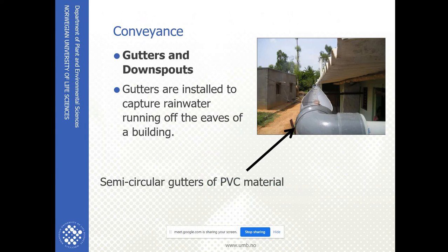Disinfecting rainwater: rainwater can be used for drinking. It is clear, has no or very little taste or smell, and comes from a well-maintained system. Rainwater may not meet the WHO drinking water quality standard, which specifies microbiological quality standards, hence some disinfection is recommended.